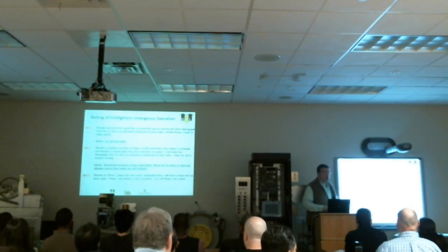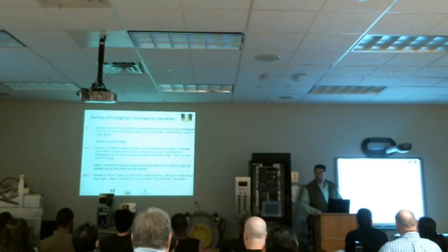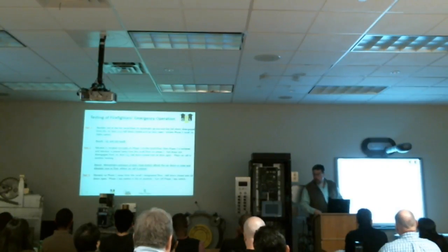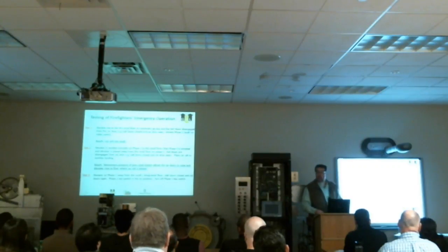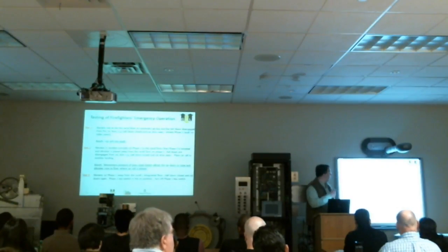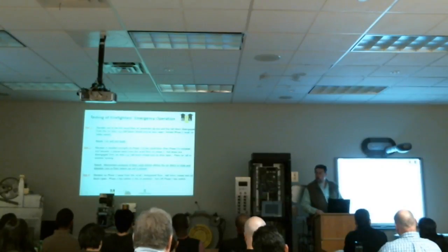And the last part of the test is if you happen to be away from the recall floor and you turn off the fire phase 2, it's supposed to go ahead and do a phase 1 recall back to the landing. So again, if we have a fault condition where the hall doors are engaged and the car doors open, and we turn the phase 2 key switch to off, you're allowed to bring the car back to the phase 1 recall. So these are the 3 tests that the DOB does to verify the fire service emergency on the door lock monitoring feature.